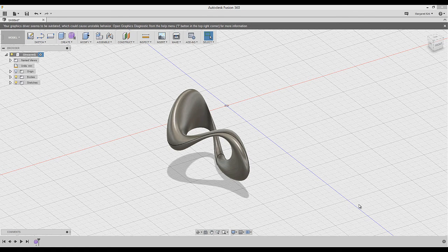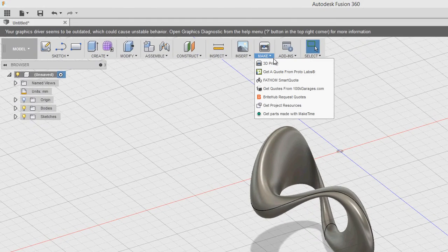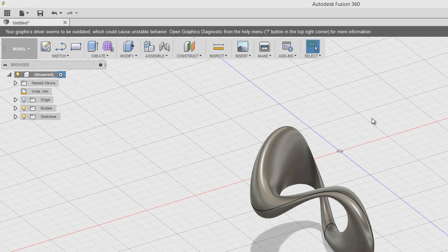So in order to create this model, we want to get it fabricated, and we have to think about how we want it to be fabricated. With the 3D printer, you could actually connect a 3D printer, and there's other resources up here too, to Fusion 360. My 3D printer has its own proprietary software. So basically we could just save it as an STL and then plug it into that software. And it's going to generate the slices to make the form itself.